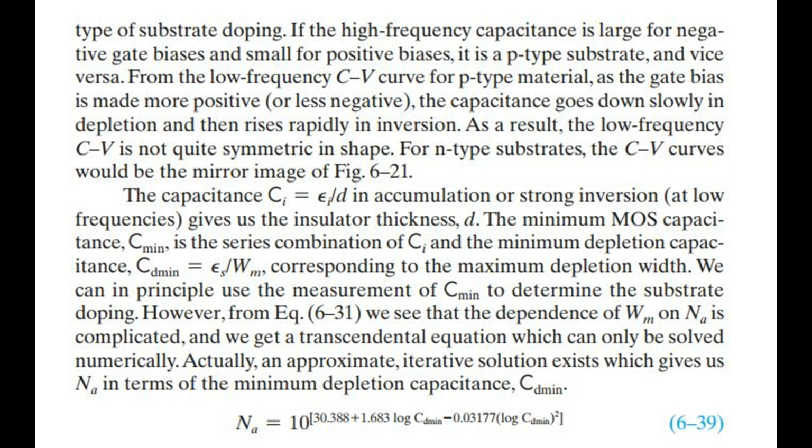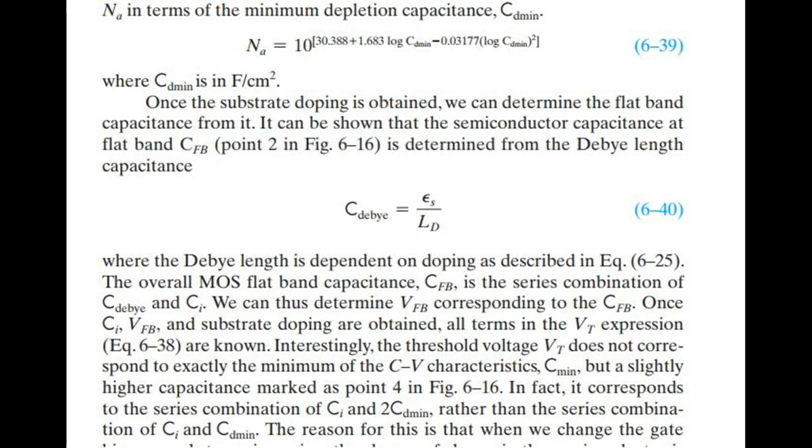Actually, an approximate, iterative solution exists which gives us Na in terms of the minimum depletion capacitance, Cd min, where Cd min is in F/cm². Once the substrate doping is obtained, we can determine the flat band capacitance from it.